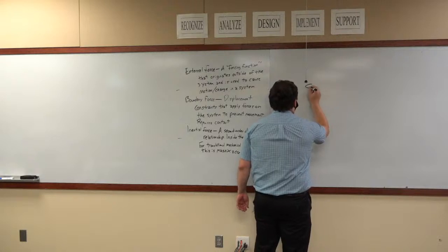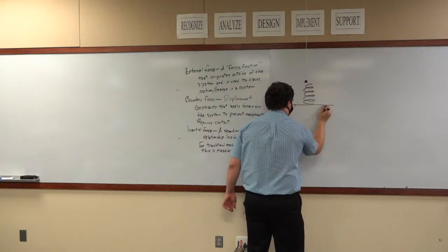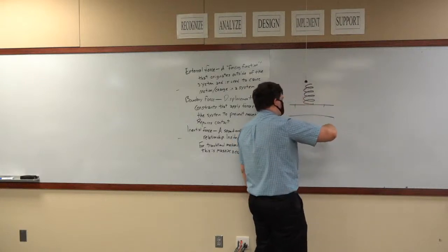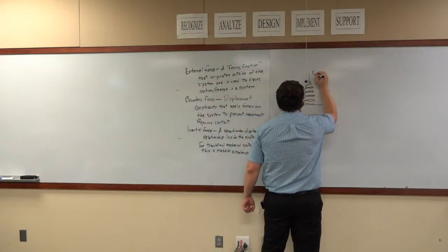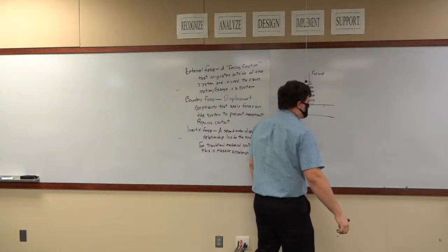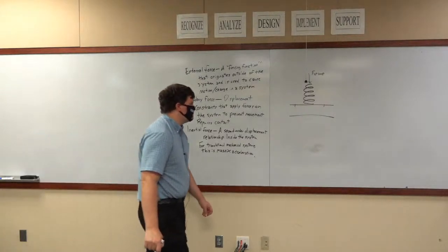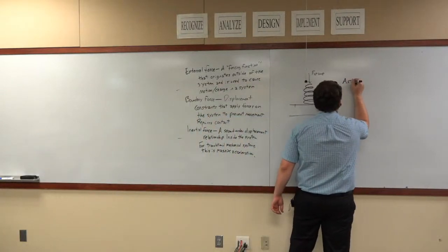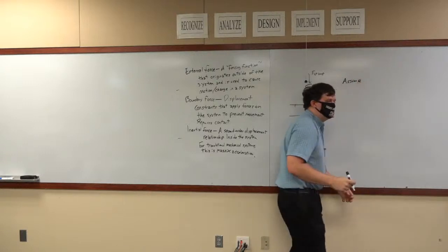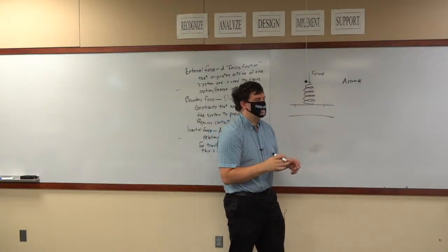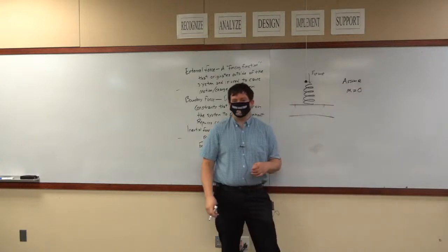Now what we're going to do is we're going to mount these cutting blades onto a spring. Okay? And that's going to go down and it's going to press on this surface, it's going to cut into it, and we're going to apply a stamping force directly to this spring. Now we're going to assume, and this is a huge assumption, but if you have a low mass system, you can usually assume this if your math turns out okay. Assume m equals 0 for the system. It's going to make our math a lot easier.